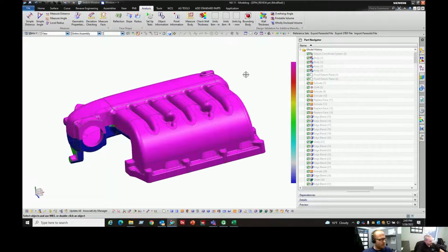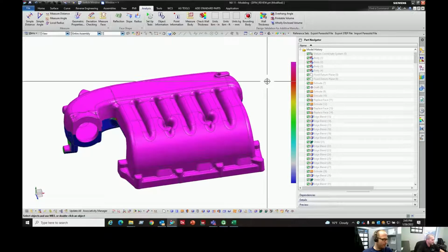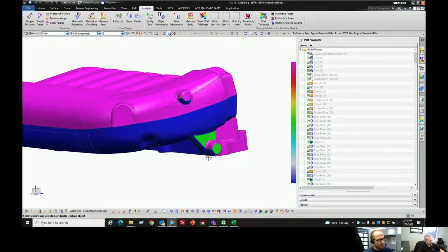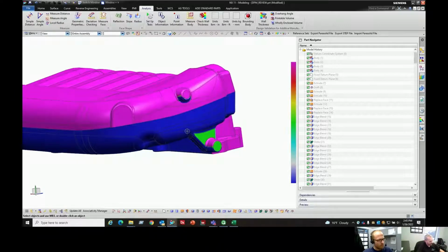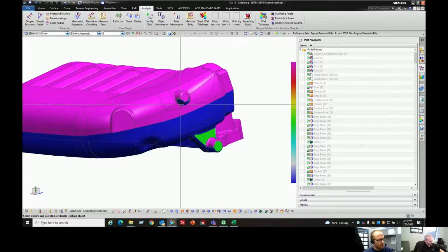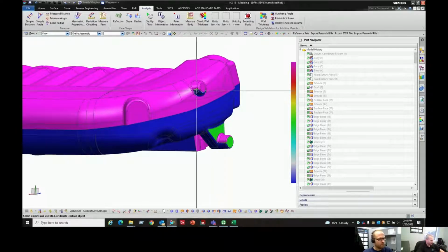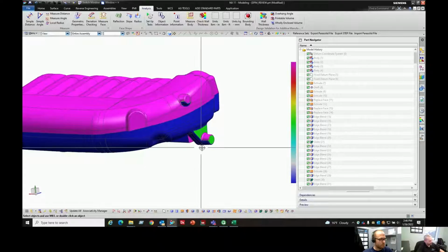It looks like there's some areas of green on the left there. Was that on purpose? So this is the area that I had discussed earlier, where we needed to keep and maintain this shape. The only way to get this, if you didn't want to have a core, would be to load this up all the way to the parting line. Well, it's not functionally wise, that's not what anybody wants. It adds a lot more mass to the casting, and so this one did require a core in this area.